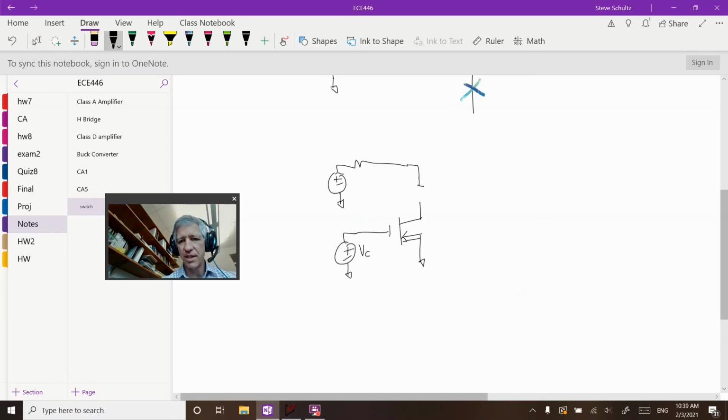Now lots of times in LTspice we're going to put a little resistor. So if this is like 10 ohms and this is 1 milliohm, this one's just to measure the direction. And then let's just do like 20 volts up here, or just our power supply voltage. And so we want to look at our relationship of voltage and current.